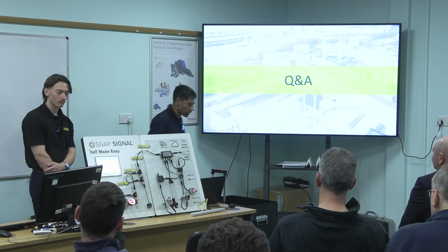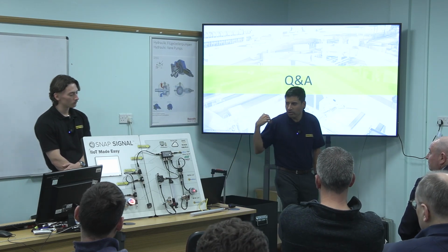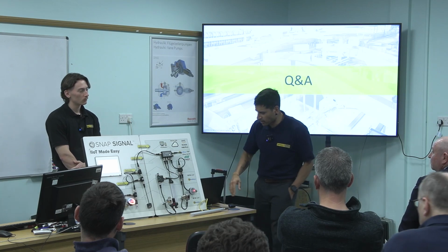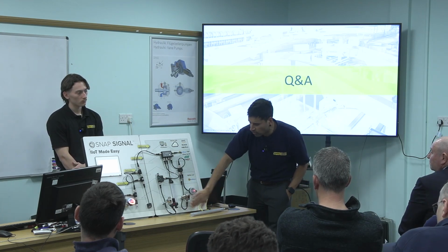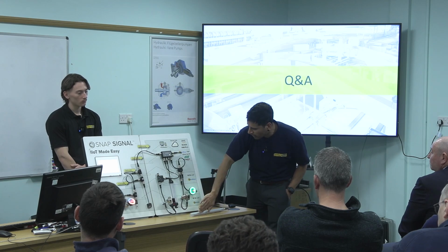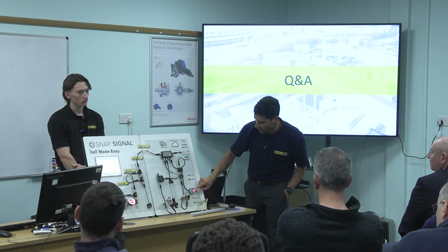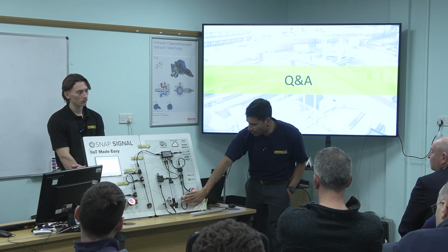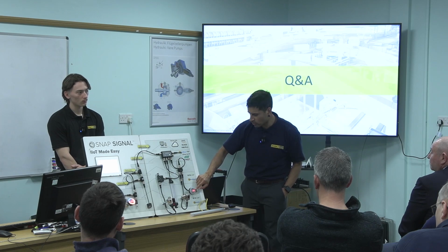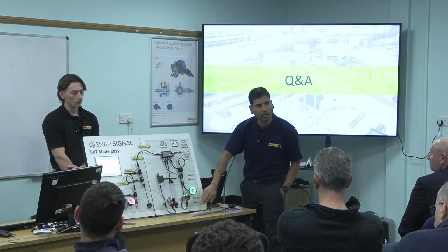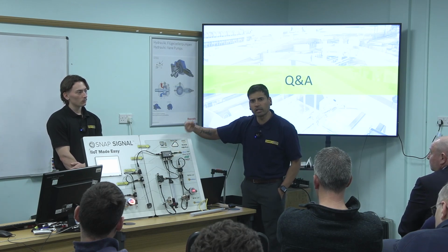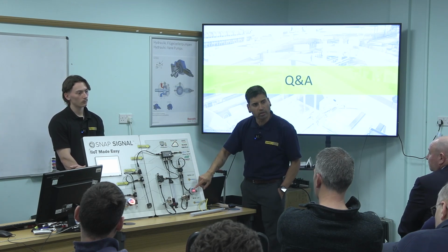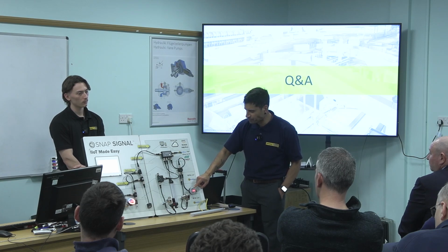This is our demo as well. This is pretty much what you've seen on the screen. So that's a Modbus light. All that's doing is taking a switched output from the sensor, and you can see the lights lighting up and it's showing a count. Because it's Modbus, it's taking the discrete signal into the controller, and the controller's doing an increment to bring on the Modbus register on the light.